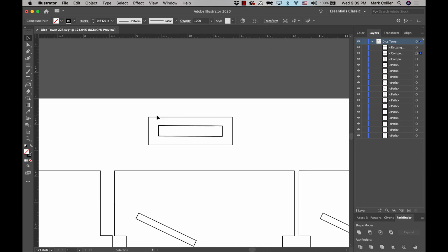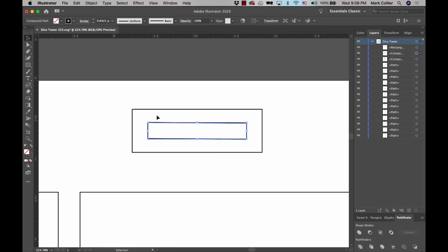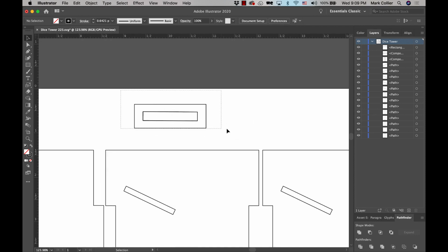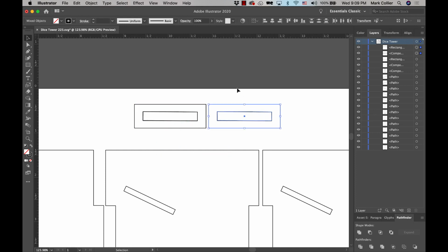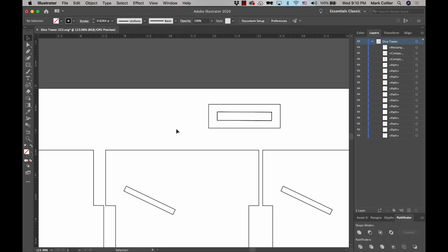So now I know that I've got a slot here that will definitely fit, but it's probably going to be a little loose. So just to save time, I would usually select both of these, copy and paste, put it right next to it if you want, right here. And then I would go ahead and edit this one to be a little bit smaller. How about maybe 198, okay? So just a tad bit smaller. I would go ahead and cut both of those and see which one fits better. And then if you need to, make one more edit, but you'll probably get there within 2 or 3 slots and you'll have it perfect. So let's say that this one right here is the correct one. I'm going to go ahead and delete this other one just so it doesn't get in my way and distract me.